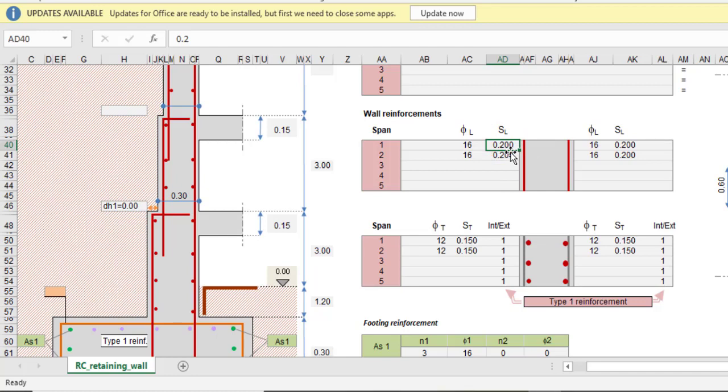But actually, I told you, you can use this template for your column. You can also use it for your retaining wall, okay. So the spacing is there instead of the number, so you should know how you manipulate that at the end of the day. So you can just ignore what the spacing is. What you should be concerned about is the diameter, because you have to edit the label of the column at the end of the day. Then here just make it the same thing.